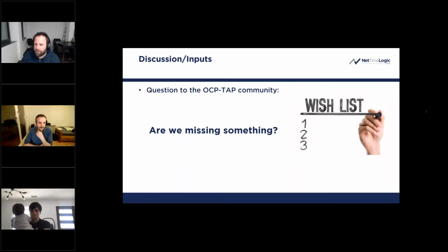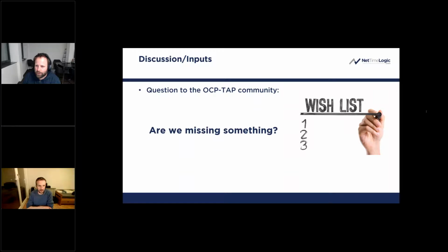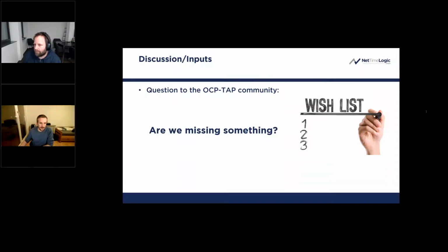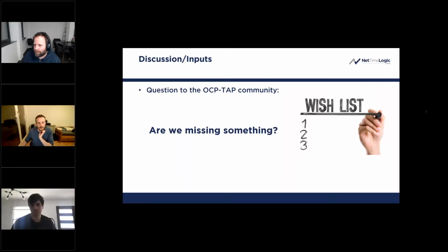I don't know who's familiar with that, but it's an on-chip bus, multi-master and multi-slave capable, with interconnects. x86 is one source to connect to our cores, but of course you can also instantiate a MicroBlaze CPU or a RISC-V or whatever softcore CPU you want and talk to the cores as well. So it's a shared bus.